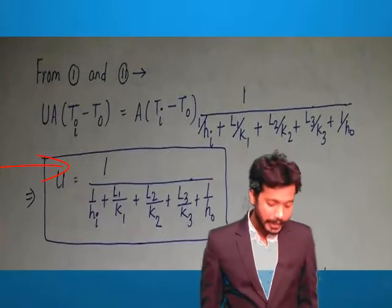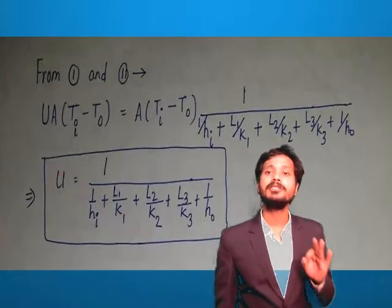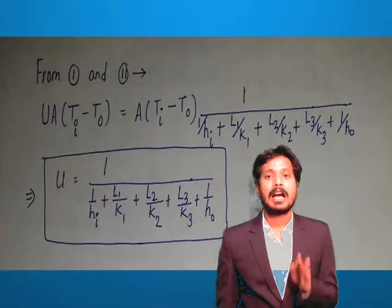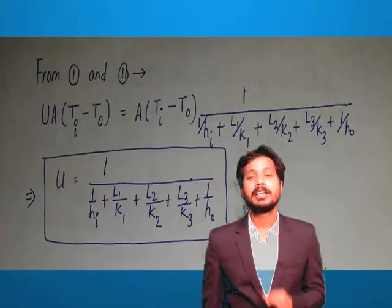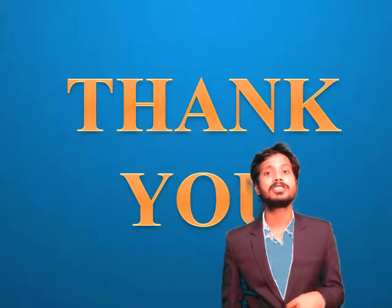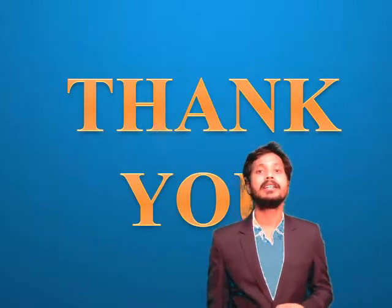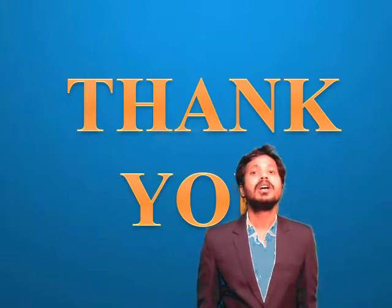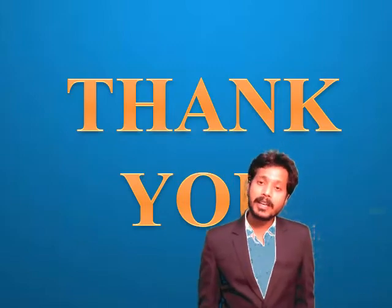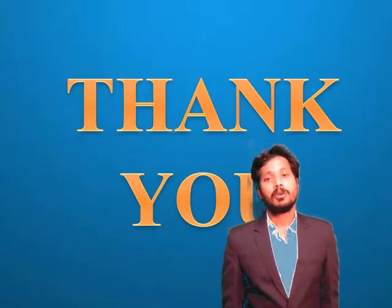Okay, before I end this class, let's revise today's class. Today we discussed the amount of heat transfer through a slab and through a composite slab. In our previous classes we had a formula for heat transfer through a single slab, but today we discussed the composite slab, and the formula of heat transfer through the composite slab including air inside and outside comes Q equals A into (T1 minus T2) divided by (1 by Hi plus L1 by K1 plus L2 by K2 plus L3 by K3 plus 1 by H naught).